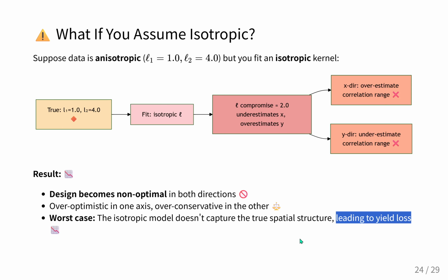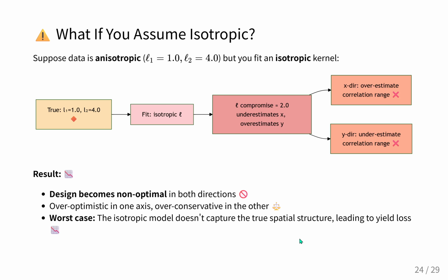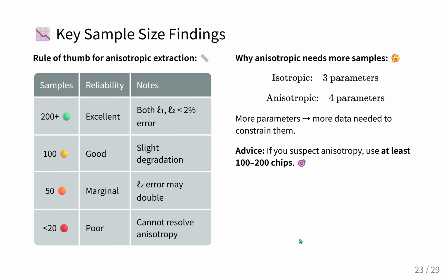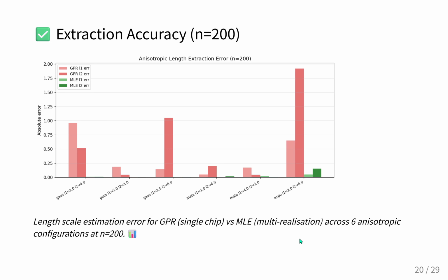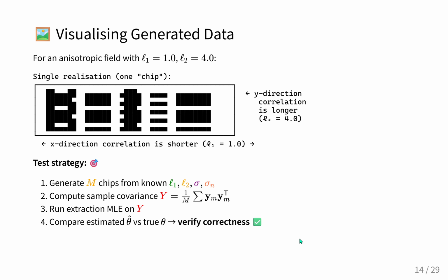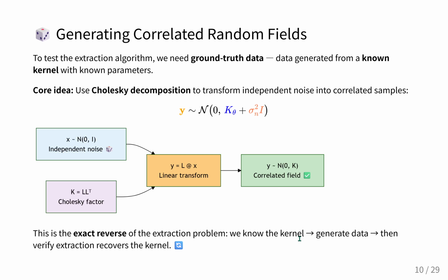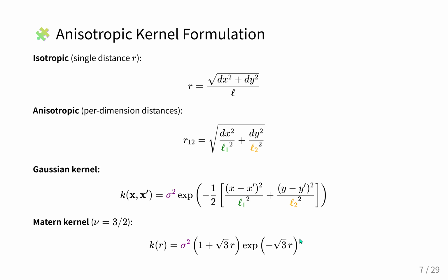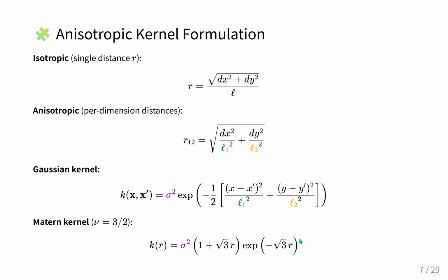So if forcing a rectangle into a square ruins our yields, how do we upgrade the math? How do we build a model that actually understands the grain? This is where the presentation moves us to a four-parameter model using Gaussian process regression. Now, Gaussian process regression is basically an incredibly advanced way of predicting the unknown based on the known, right? Exactly. If you measure the thickness of a chip at point A and the thickness at point B, Gaussian process regression helps you guess the thickness of every point in between based on spatial correlation.